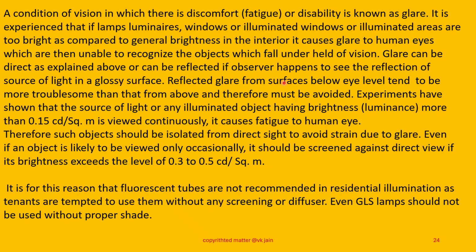Reflected glare from surfaces below eye level tend to be more troublesome than that from above and therefore must be avoided. Experiments have shown that the source of light or illuminated object having brightness, that is luminance, more than 0.15 candela per square meter, if viewed continuously, causes fatigue to the human eye. Therefore, such objects should be isolated from direct sight to avoid strain due to glare.